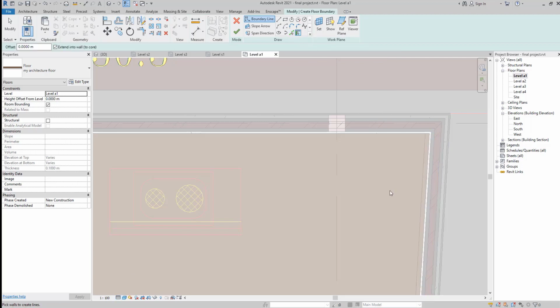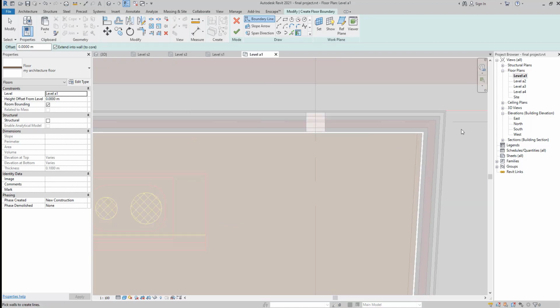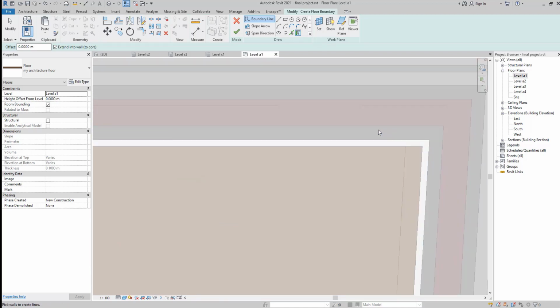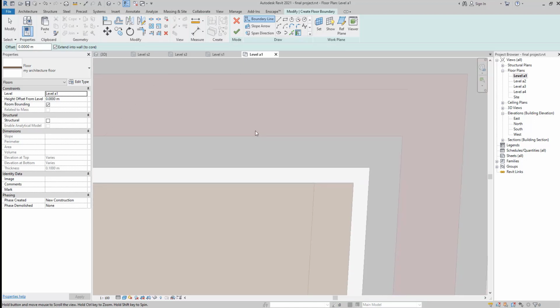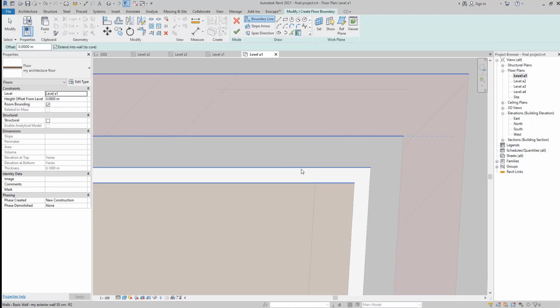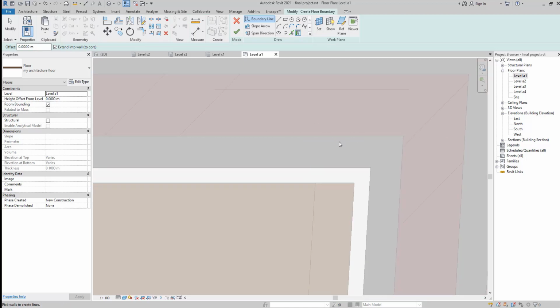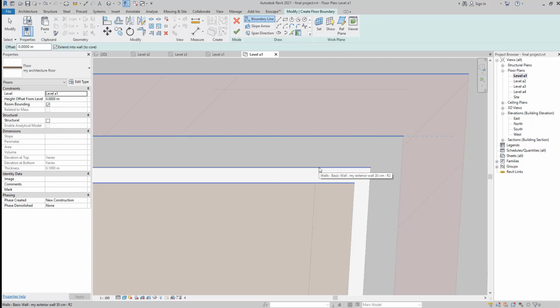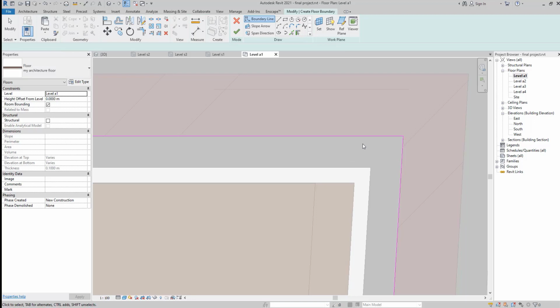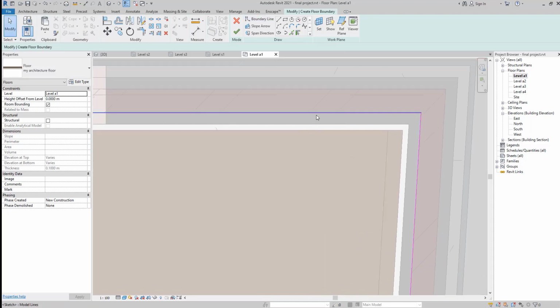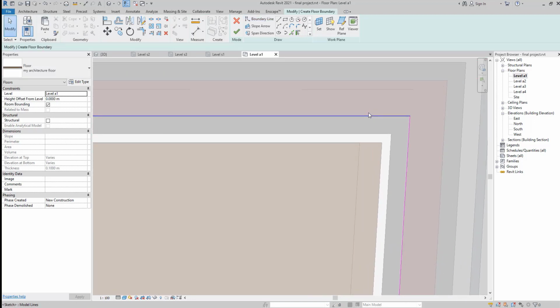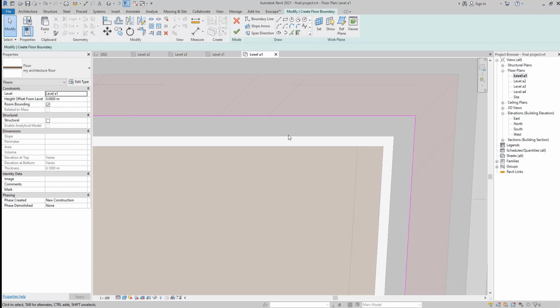Both are working now. The layer where you need to start creating your floor is required to be after your air thermal layer. So this line is the perfect line here, or even you can create it from, for example, the last layer, for example your finish too.